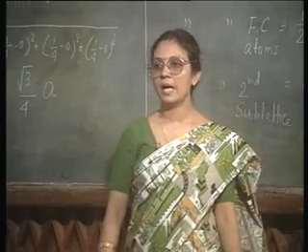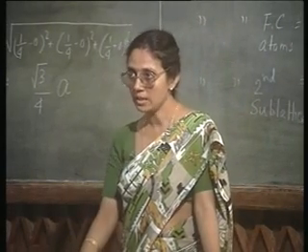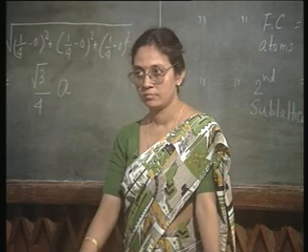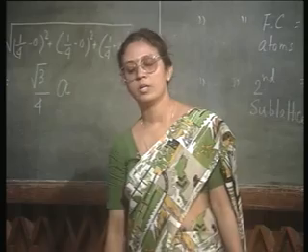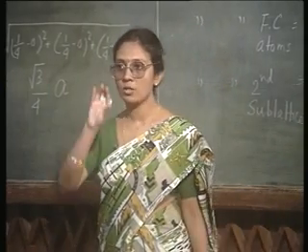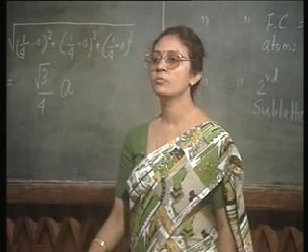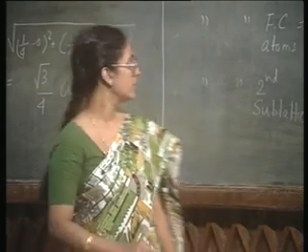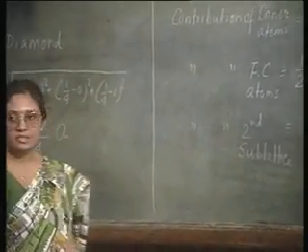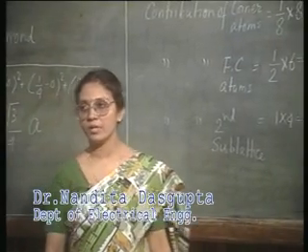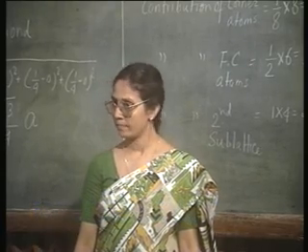So, I have a total of 8 atoms in the unit cell. Agreed? I have a total of 8 full spheres. Considering the hard sphere model, I have 8 full spheres inside the unit cell, and each atom can have a maximum radius of root 3 by 8 a.